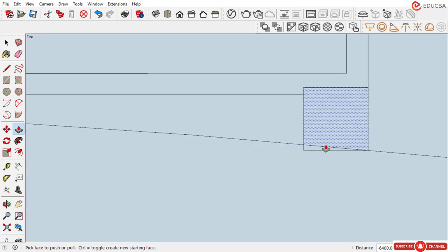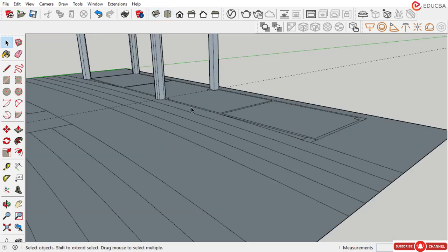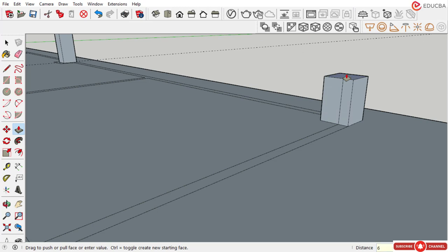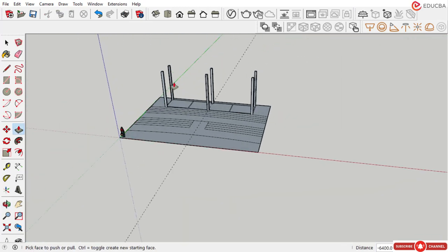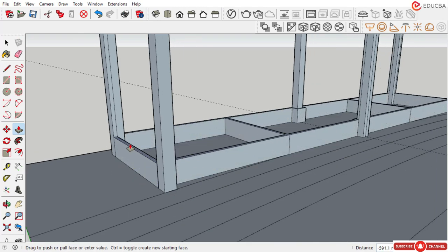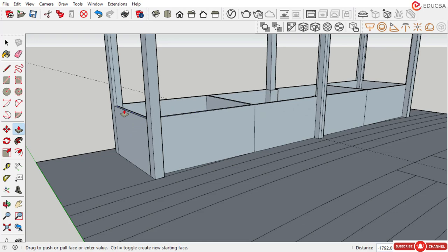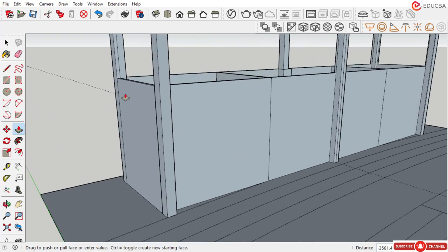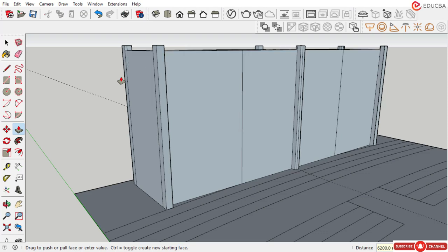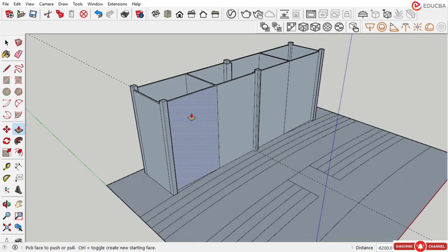Again come to this side. As we can see, the column is not completed, so delete this and this will become a column. Now in the 3D view we can extend this column 6400, again from here 6400. So these are the 6 columns I have designed for the cabin area. Now let's start the wall extension. As we can see, the entire wall is increasing with the height. Here I will give a height of 6200, because 3000 plus 3000, ground plus 1, as well as the slab thickness 200. So this is my actual cabin area, and later on we will convert it into levels.